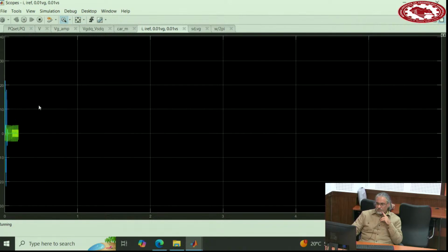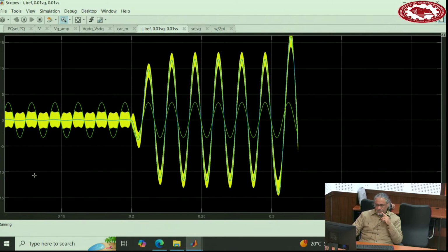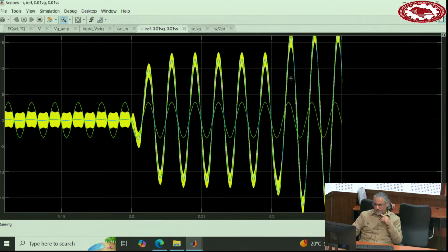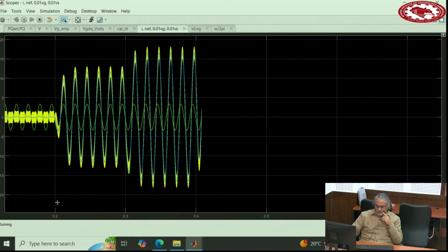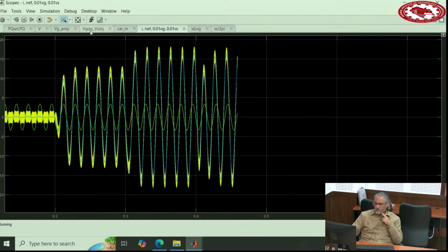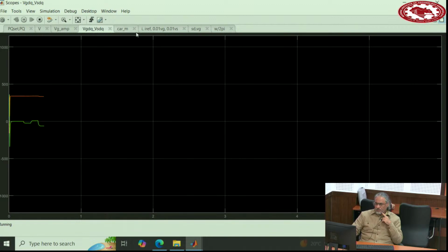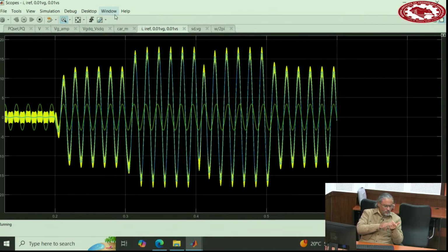Okay, so this is the scenario. You see, time is 6 seconds now. All the other simulations we ran before were in the order of a fraction of a second. This time is much longer, because I wanted to run all these cases that I showed you in multiple figures in one simulation. So here is the point that you apply the initial set point, for instance, real power and reactive power. And this is in grid connected mode all the way up to, I think, 0.8 or something. Different disturbances in grid connected mode will be real power, reactive power, grid voltage fault, and these things.